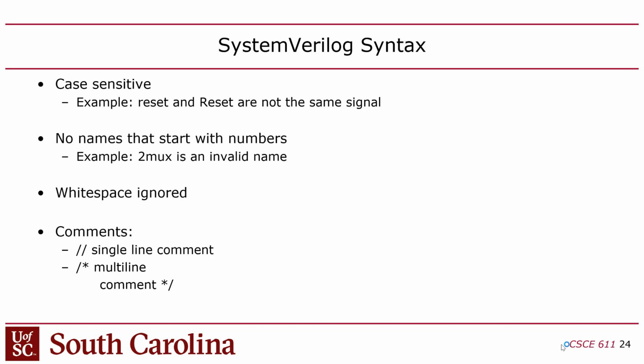Okay, so let's talk a few more things about SystemVerilog syntax, because after all, this is just another programming language, essentially, that you're learning. So it's case sensitive, which shouldn't surprise you because all the languages you guys have used are case sensitive. The reason they bring this up in the book, though, is because VHDL is not case sensitive because it was derived from Pascal, which is not case sensitive. So that was another lineage of programming languages that's not case sensitive, but Verilog is.